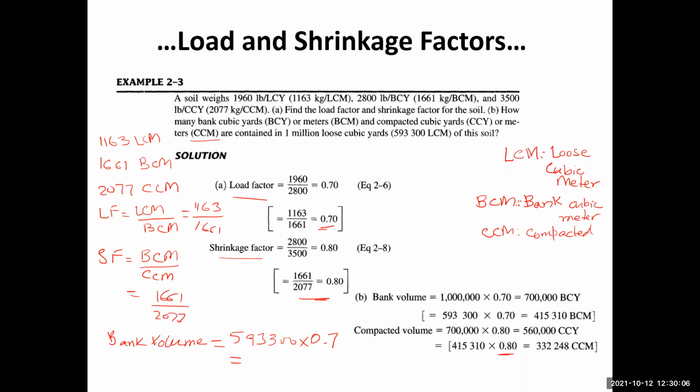You will multiply the loose volume with the load factor to calculate the volume in the bank condition. Or if we want to find the volume in the compacted condition, then you will multiply the volume in the bank condition with the shrinkage factor.